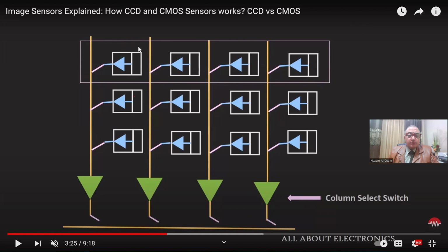And at the pixel side, we have a potential, instead of the potential well, we have a sort of CMOS capacitor that can be used for charging and discharging. When applied to light, it accumulates the charge. Then it will be, let's say, discharged through the filters and the accompanying circuitry in the CMOS cameras.